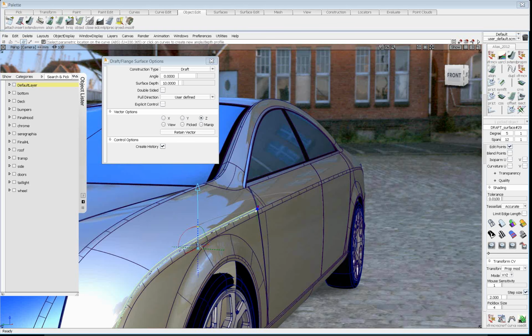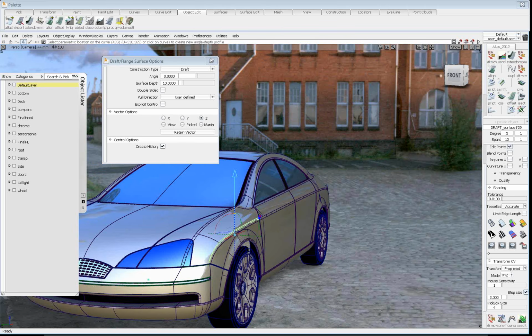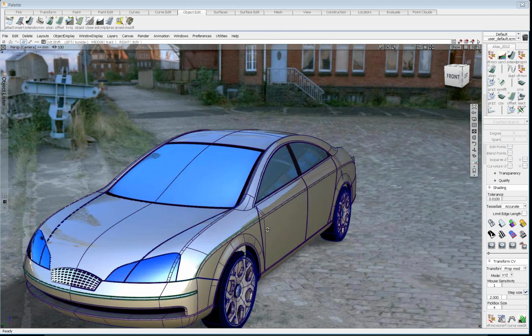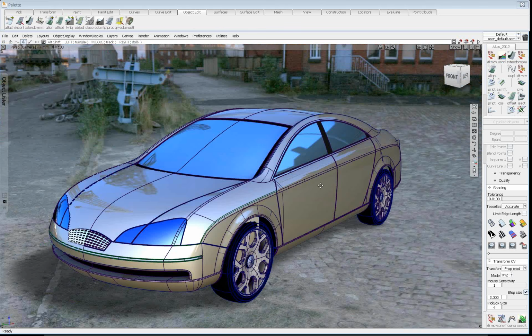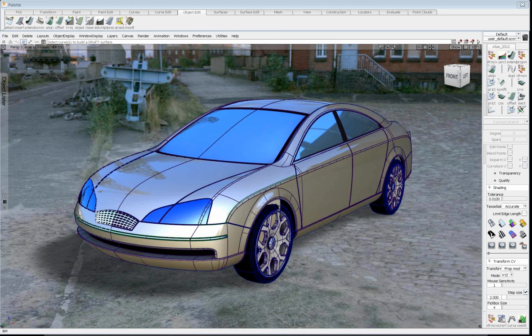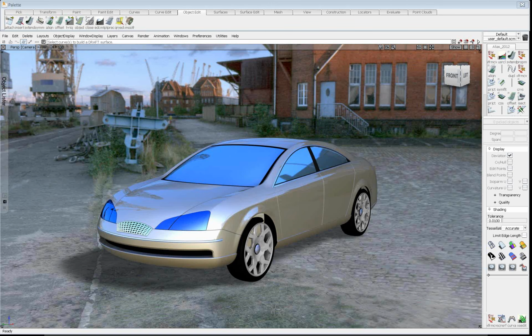Final question that I think coming from us would be, are fillets G2 continuous on panel gap? Not in the 2012 release. They're just G1 or tangent continuous. So we recognize, again, people have told us that it's fairly important that we make sure that we can get them G2 as well. And so that's a focus for our current development cycle, and hopefully we'll be seeing it in the near future. So center line and the ability to do G2 fillets are recognized as important to customers now that they've seen the panel gap.